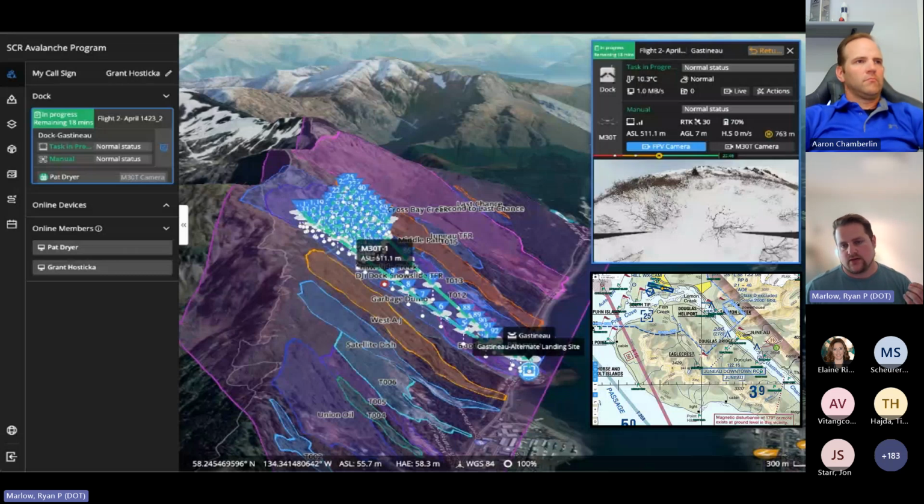We're utilizing a lot of RTK, and then of course post-processing that data for reliability. But same thing, we're just allowing for us to do change detection, do slope prediction for runout models, but we're just looking at the volume pre-post storm and then compared to a bare earth model and detecting how much volume is now up there versus what could possibly hit the road.